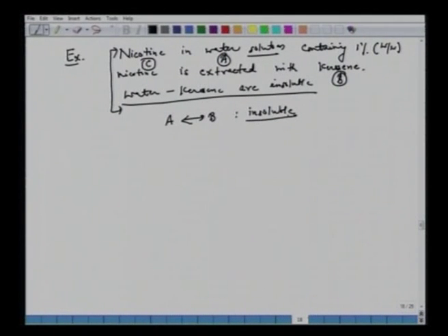All right. So in this case, we said that this type of diagram will also work, except that this becomes unnecessary because for A and B we don't have any phase here. You can have phase on A and C and C and B here. So if we take a solution of A and B and allow it to settle, we can have some separations here, or between C and B. So in such cases we look for y versus x, that's sufficient, or y prime over x prime, solute-free basis.